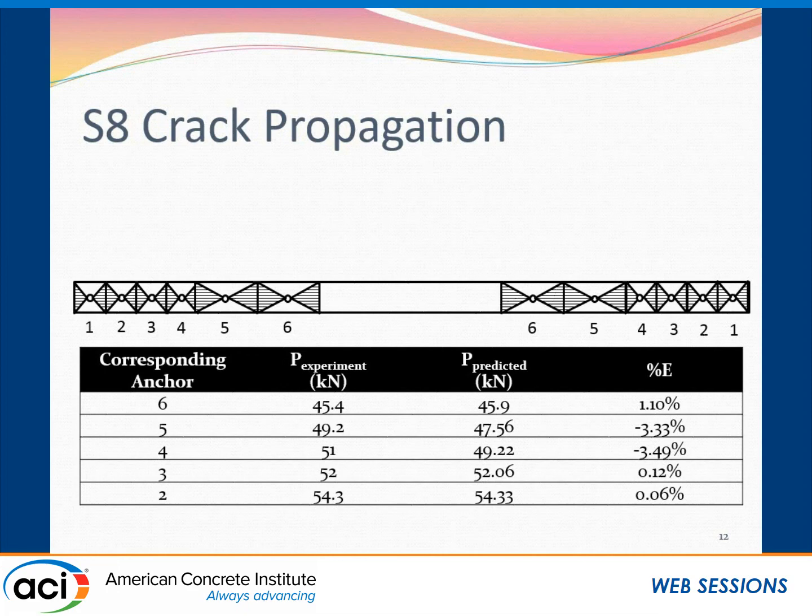I was talking to a contractor who says he does a lot of this work, and I said, what about the concerns about fire? And he said, we just put fireproofing. Exactly. It depends on the county and where you work. There are codes, and some counties refuse to accept FRP strengthening, they are very strict, but some who are progressive actually look at the test results and at the different techniques used to retard the fire effect, and they accept that.